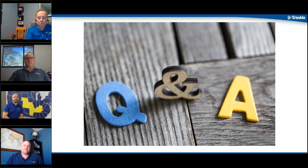One of the things that I always recommend is finding column lines. So if you're inside of that existing space, you can't get to a building corner, a column line. And that's where Kevin was showing that offset of being able to set up a pattern of 4-foot offset of that. Sorry, I can't talk. But that's just allowing you to be able to come off 1 foot, 2 foot, 3 foot, or 4 foot from that column center line and bring those out a little bit. I don't know, Bob, Kevin, or Sean, if one of you had something else you wanted to add to that.